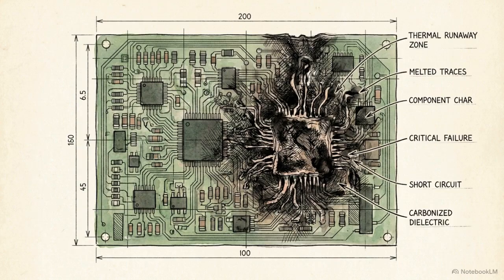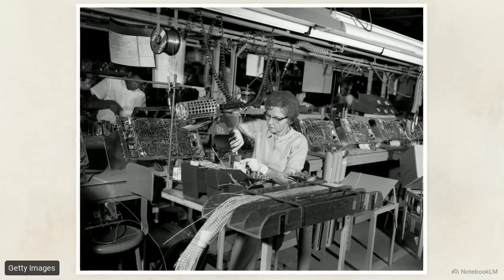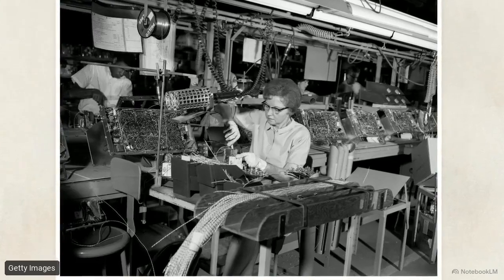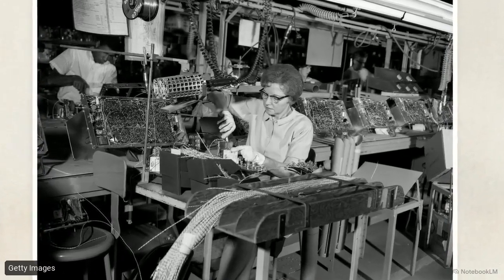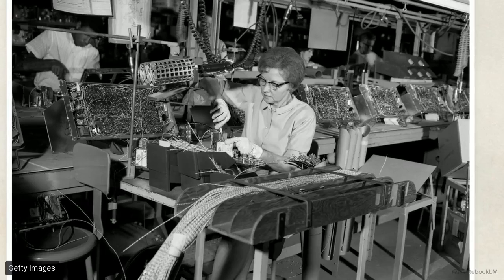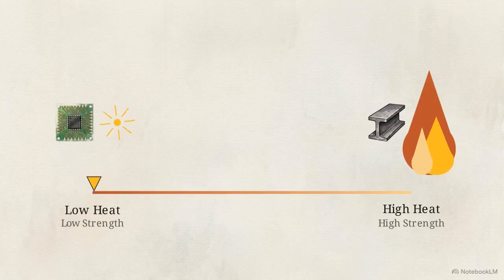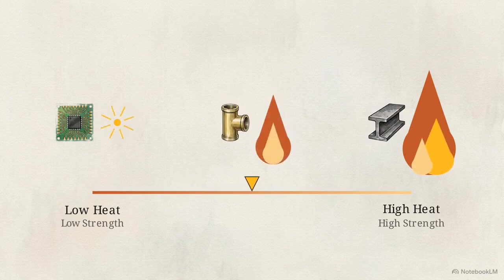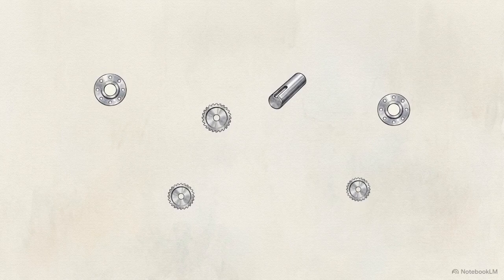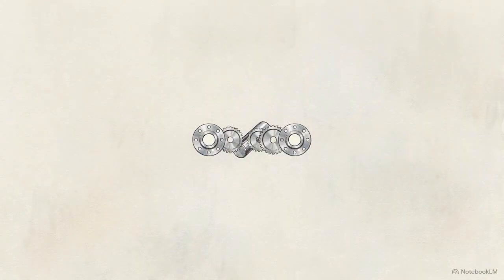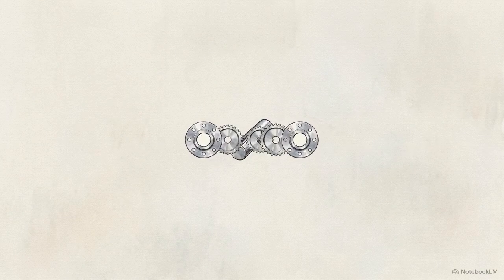But welding requires massive heat input, which will destroy highly delicate components. That's where soldering comes in. We use low heat, melting only a separate filler alloy. The delicate electronic base materials remain completely solid. Intermediate processes like brazing exist along this same spectrum, allowing engineers to balance the structural strength of the joint with the amount of heat the materials can tolerate. These joining processes scale our thermodynamic principles up or down, unifying separated geometries into a single cohesive machine.